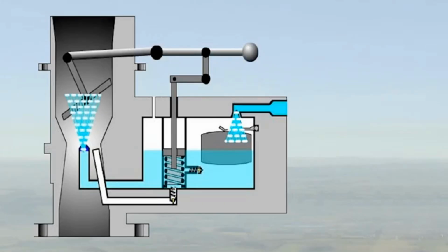If the throttle valve is opened quickly, airflow responds almost immediately, and a larger volume of air flows through the carburetor. The fuel metering system, however, responds less quickly to the changing conditions, and a temporary weakening of the mixture will occur, known as a flat spot, or at worst, causing a weak cut, before fuel flow again matches airflow.